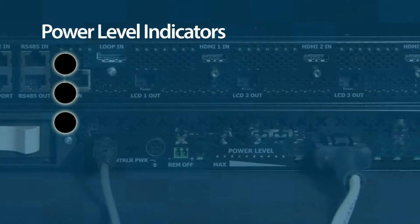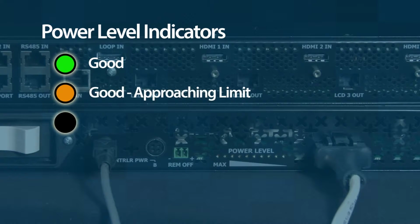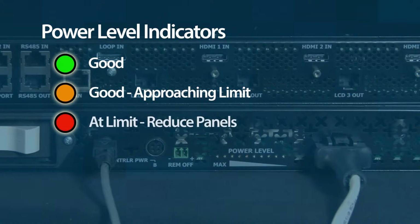When the power level LED indicators are green, the power level is good and other displays may be added if necessary. If the LEDs are orange, the power level is good but approaching the limit. If the LEDs are red, the power level is at the limit and the number of displays it is driving should be reduced.